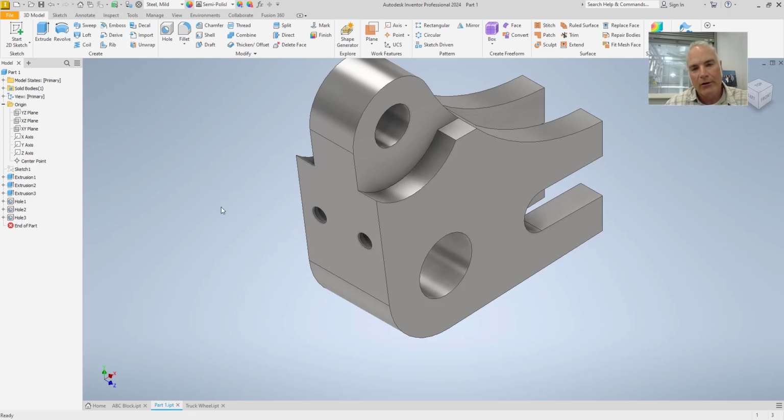Now again, earlier I said the importance of including sketch geometry is if my part changes, these features will change as well. So what I did was, remember, when I created that sketch, I included that edge right there and that edge right there in the sketch, and then I dimensioned the center of the hole based on where it is from that edge.